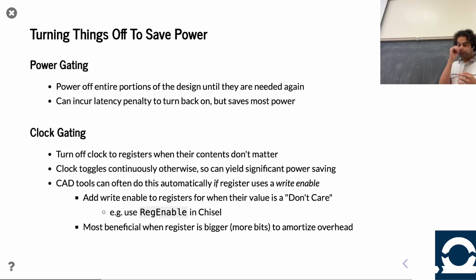You'd be surprised how some architects and designers are very clever. Even in your smartphone, for example, because of things like the protocols for your data transmission, the cell radios know what times you're supposed to be sending and what times you're not. So in those idle times, it knows it's going to be idle. It can actually power gate part of that circuitry because it knows it's not going to be used. Because it's very predictable, I send at this time, receive at this time, and then do nothing in between, it can put it to sleep safely, knowing when it has time to wake it up.